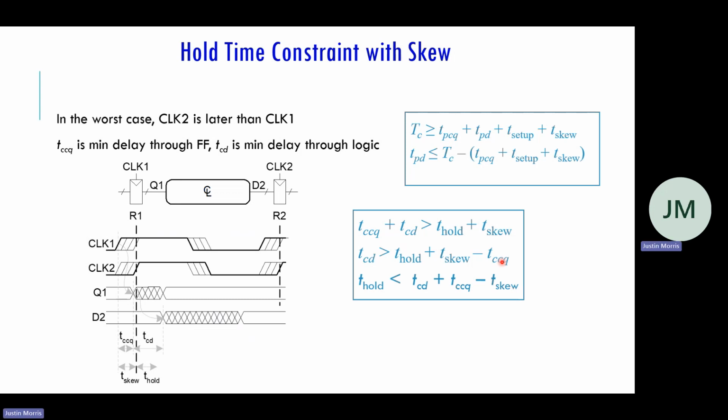And this clock skew, it's often also called clock jitter, is usually given as a percentage of the total cycle time. So if your clock period is 100 nanoseconds and it says you have a clock skew of 5%, that means that the maximum real clock period that you will ever see is 105 nanoseconds. And the minimum real clock period you'll see is 95 nanoseconds. So it varies, right? So that's why you have to include that here.